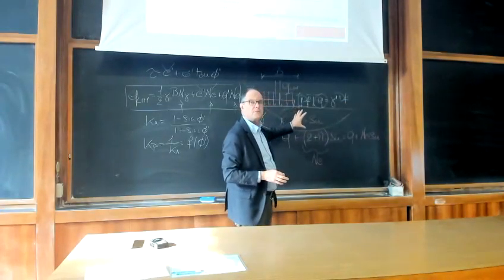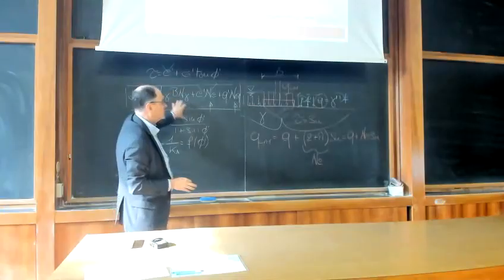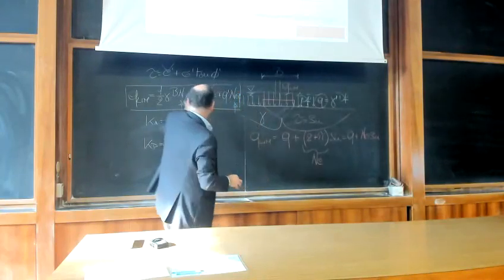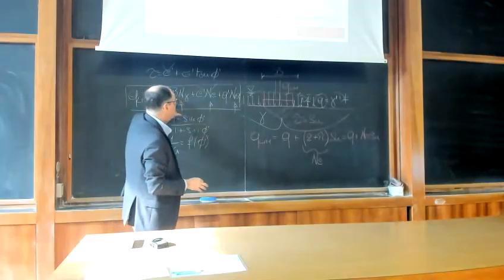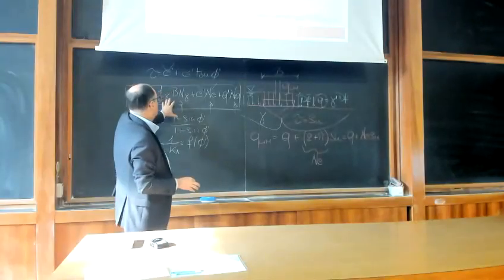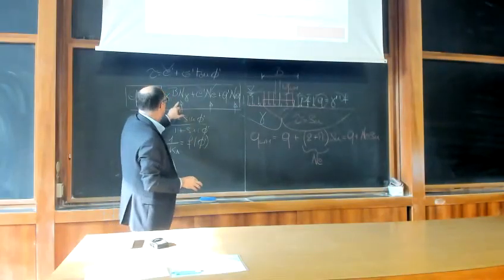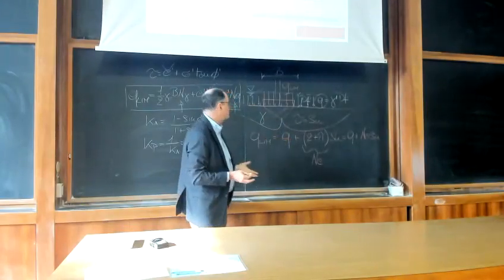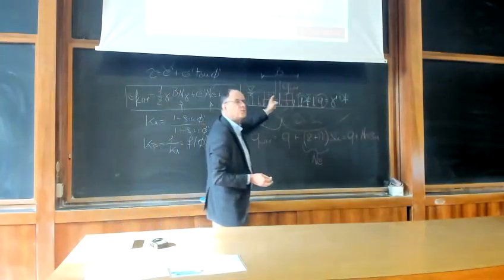Where does the capacity come from? From the only term left, which is this one, because the soil here will always have some gamma, and so this term in drained conditions will never become zero. You are left with no overburden stress, no cohesion. This is there. And you see, this depends on N gamma, which is phi, on gamma, which is your soil unit weight. This is what comes with the soil, and also with B. What is B? B is the footing breadth.